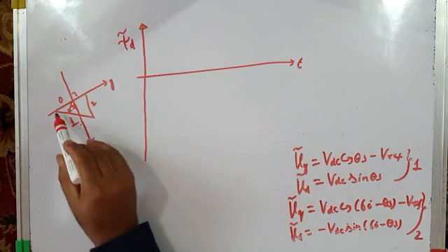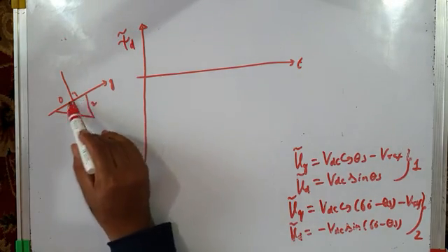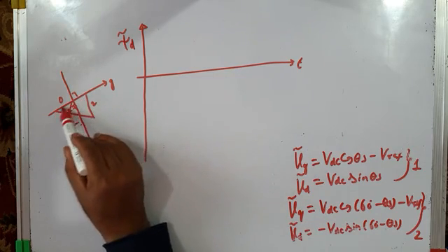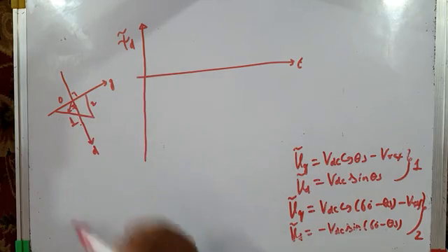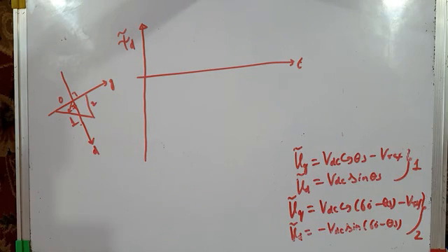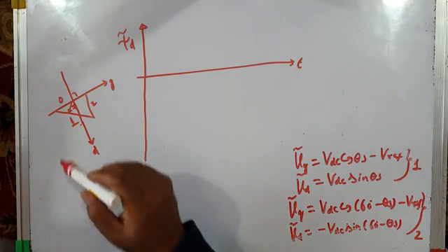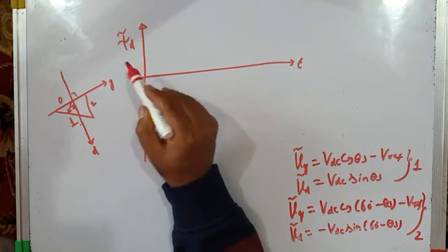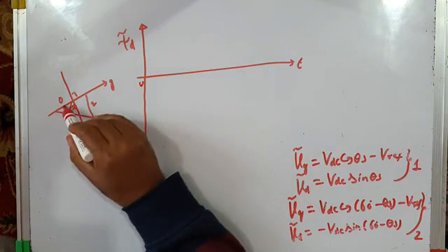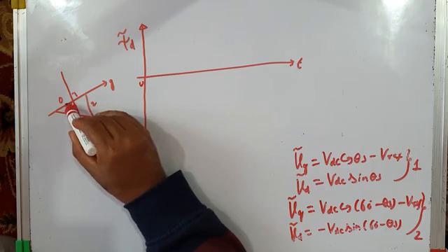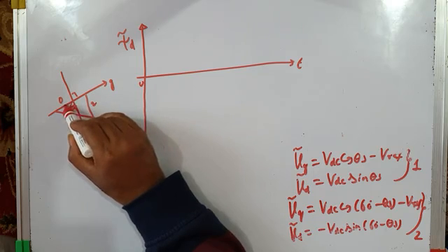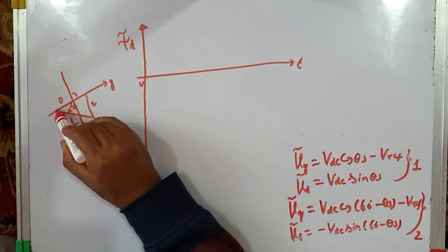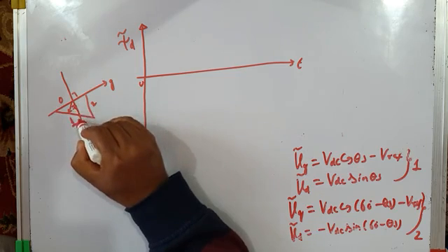That is the component of this stator flux ripple vector. This is the stator flux ripple vector which moves along this triangle. Its component along d axis is psi d tilde. Okay. Now it is very interesting to see that when null vector 0 is applied, this is our stator flux ripple vector. It moves along this, and it has no component along d axis.